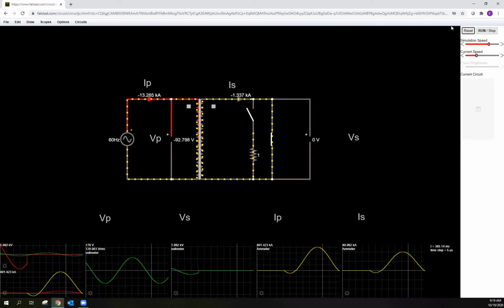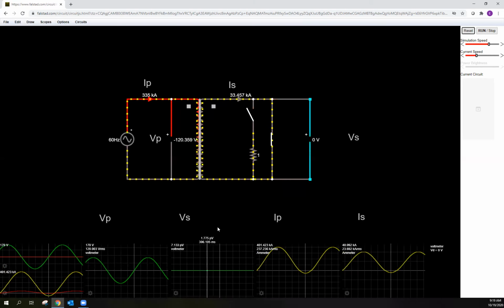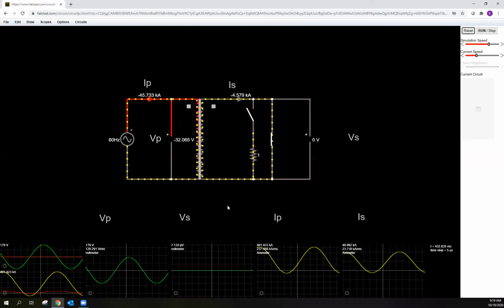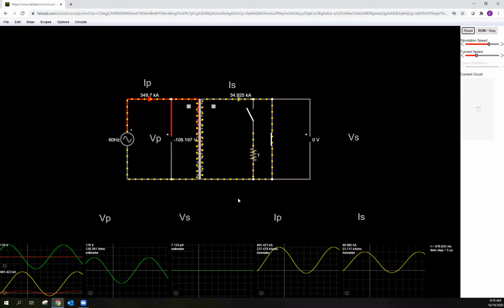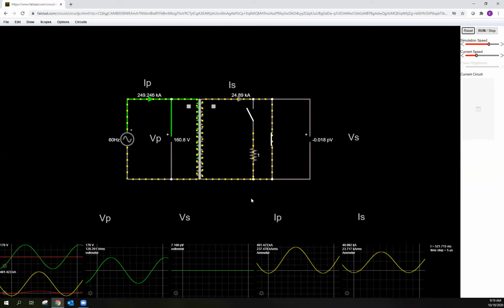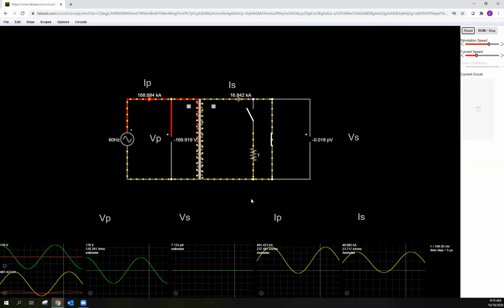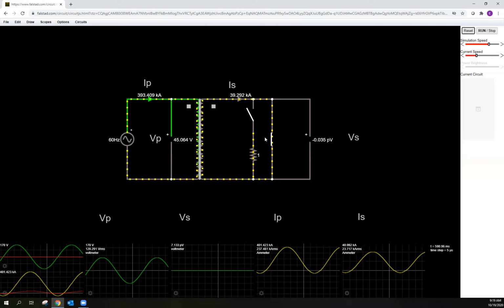Okay, it's kind of the reverse, right? For the voltage, notice no secondary voltage. So those ideal relationships, V2 equals N2 over N1 V1 and I2 equals N1 over N2 I1, are only under ideal conditions. So you've got to make sure that you're not breaking those ideal conditions.